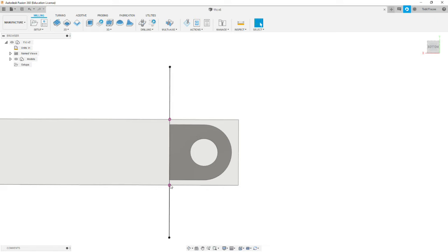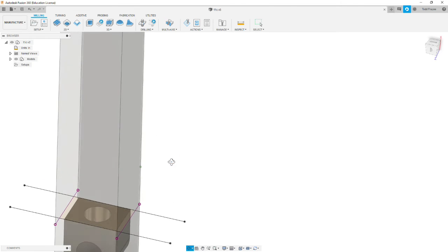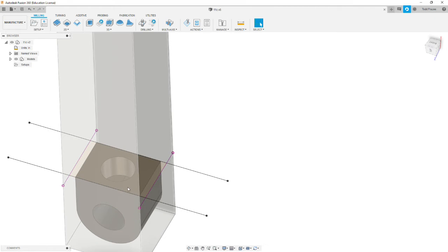After we've established the outside profile, we will then cut off the back of this. We'll part the part to the right off from the stock. And then our third operation will be to place the same part vertically in a vise and establish this hole. And at that point, all of the stock will have been removed.